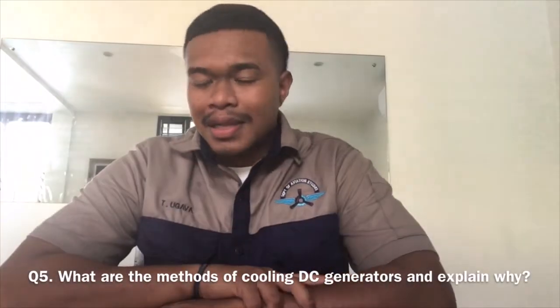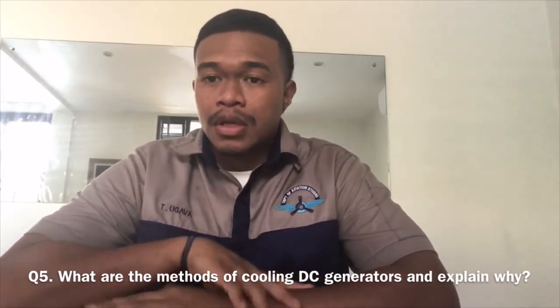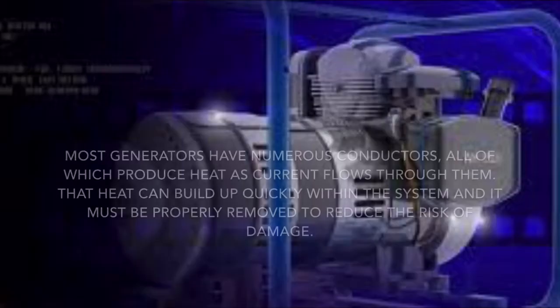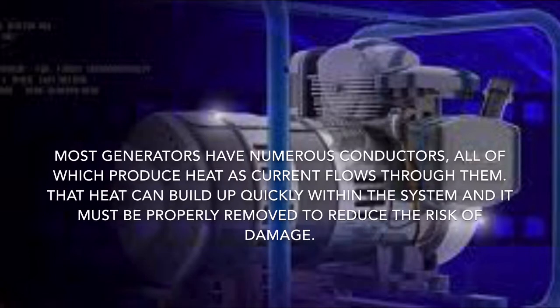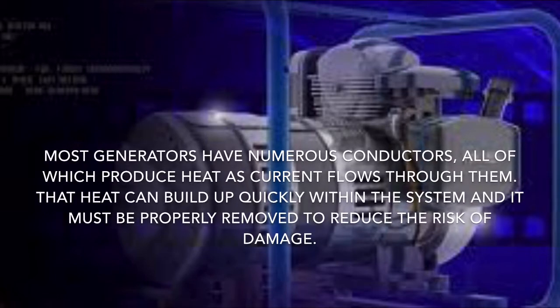Question number 5. List the methods of cooling systems in the DC generator and explain why. Before we get straight into the real explanation, why do we need to cool down generators? Most generators have numerous conductors, which all produce heat as current flows through them. That heat can build up quickly within the system, and it must be properly removed to reduce the risk of damage.